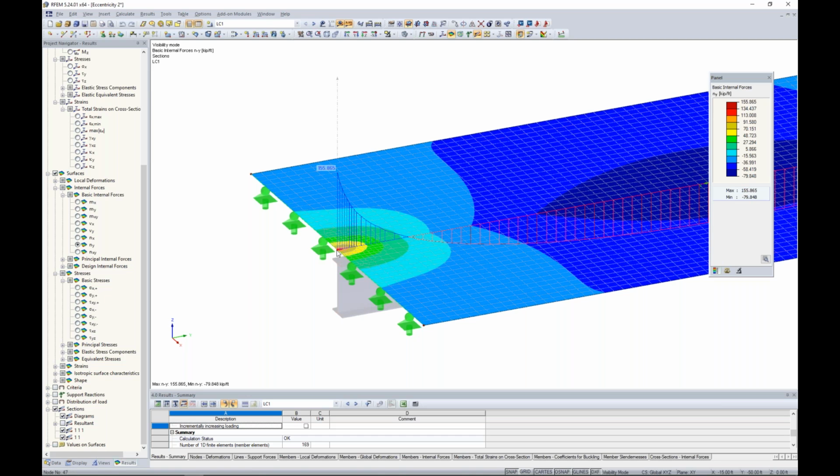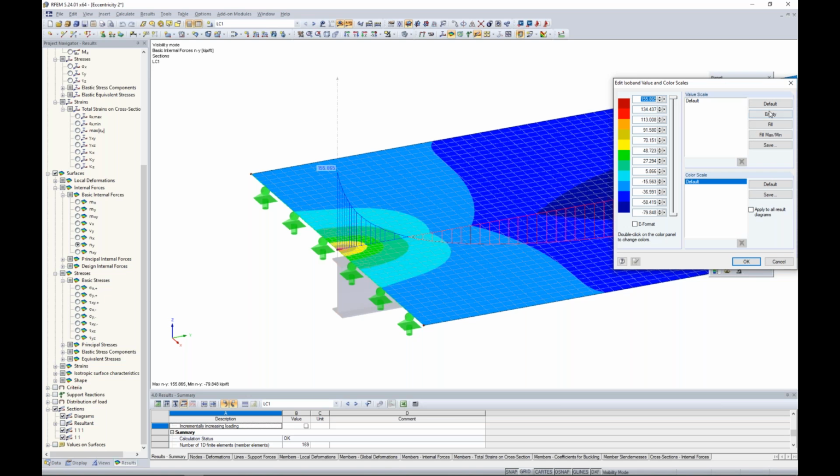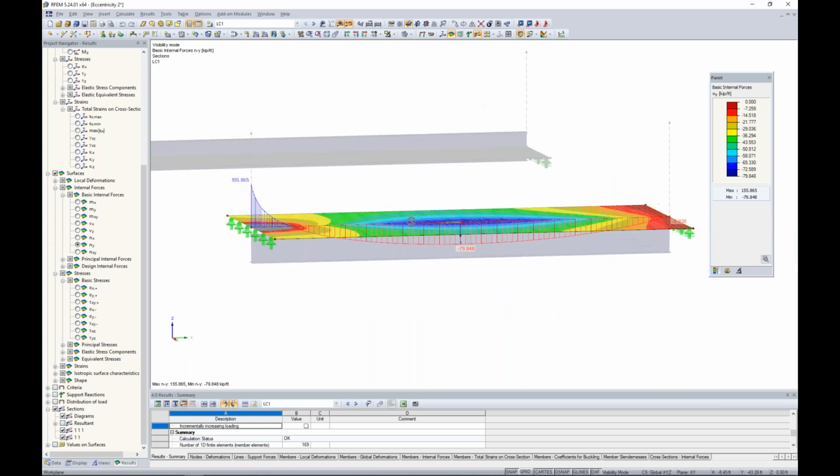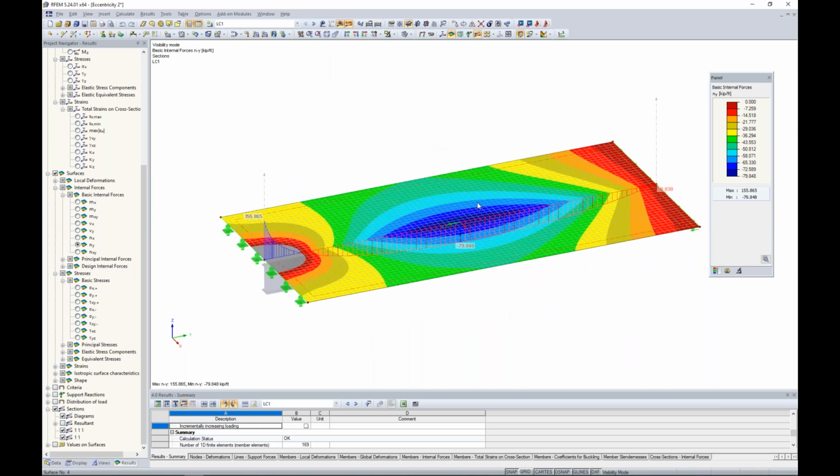So we could probably use an average region, maybe rigid links, to take care of that. In our control panel, maybe we completely take out tension and adjust this control panel to look only at the compression forces. And it's really as we'd expect. We want this slab element to take those compression forces from this applied area load.